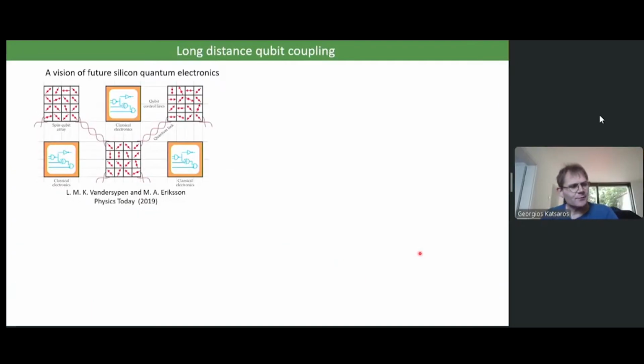So one of the big questions in the field is, okay, we can do nice n times n arrays, but how are we going to create really a scalable quantum processor? Let me remind you that with the error rate still existing, and if you think of using the surface code in order to create physical qubits, probably we are speaking about 1 million, 10 million qubits in order that you can start doing things which are, let's say, relevant for a real life application.